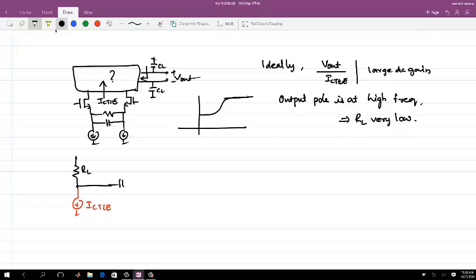So if you use a source follower, let's say you use another transistor with some bias current, and this is the node you are going to use. You can surely do it, but then you will be having a capacitance C1 coming in at this node to begin with. Surely at this particular place you are pushing the pole out. But this source follower should also have a certain common mode voltage range. And think about it, this source follower is going to add noise here without giving you any gain.